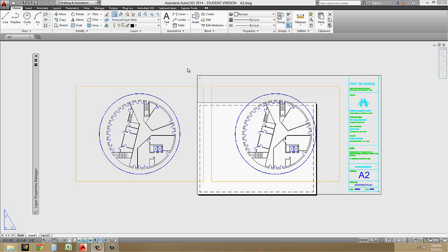That's about the trickiest part about it. And to do it, what we're going to be doing is adding all of our notes and dimensions in model space of our original drawing. Some firms will add their notes and dimensions in paper space, basically in order to alleviate that whole issue with the old way of doing the text and dimensions. But it's also very common to do them in model space.